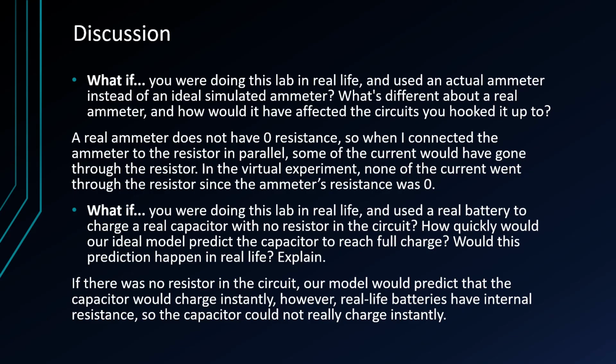And what if we did the experiment with a real battery to charge the capacitor with no resistor in the circuit? If there was no resistor in the circuit, our model would predict that the capacitor would charge instantly. However, real-life batteries have internal resistance, so the capacitor could not really charge instantly.